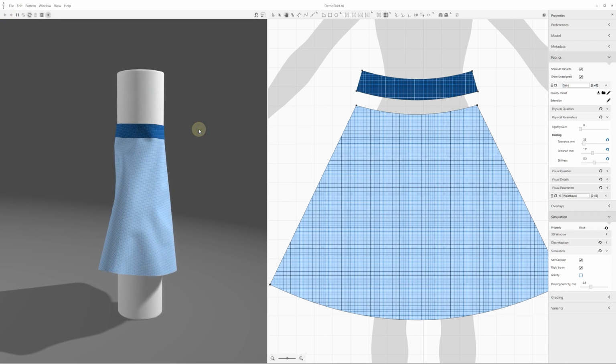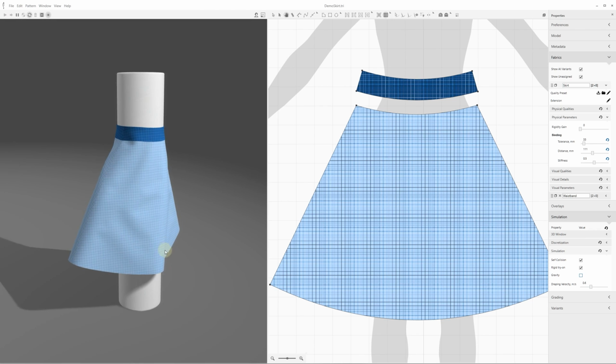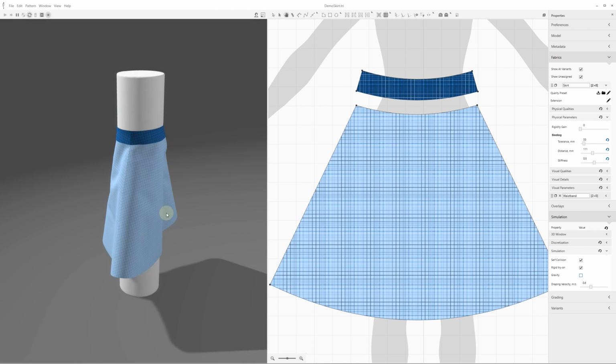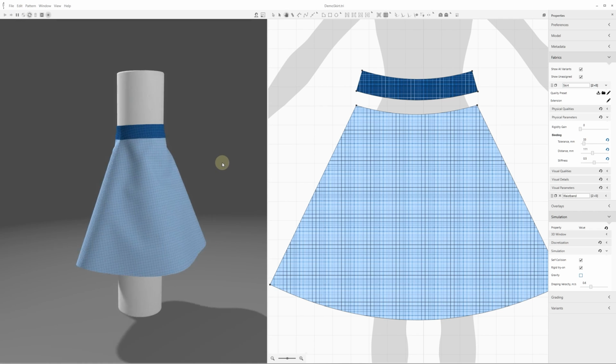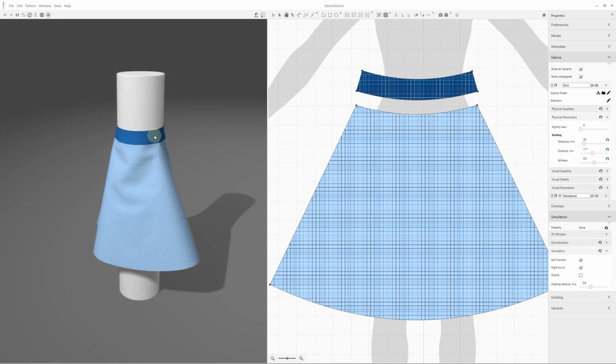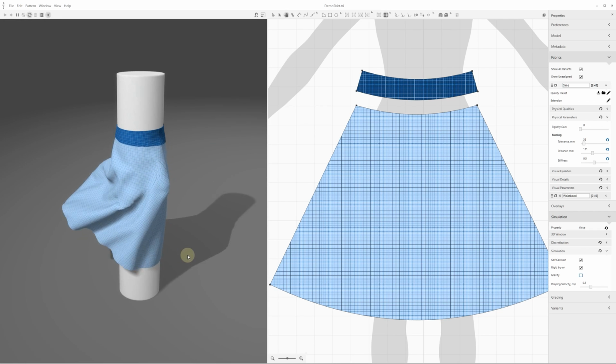Let's start the simulation and try to adjust the skirt shape before the binding takes effect. When we stop the simulation after that, the system turns the wrapping on, or in other words, it remembers how the cloth triangles are positioned relative to the mesh surface. Starting the simulation again turns the binding on and the parts of the skirt that are within the tolerance gap become bound.